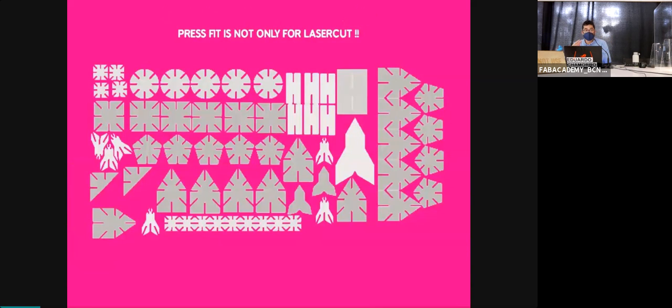When we produce cuts on the CNC, we also need to use nesting again. We already mentioned it in the laser cut; it is a technique to fit your parts together to save material. We already saw that we can use Deep Nest or Nest.io, which are online open source tools, to nest your objects. There is also Rhino Nest or Grasshopper Nest. All the different software already have alternatives for nesting.